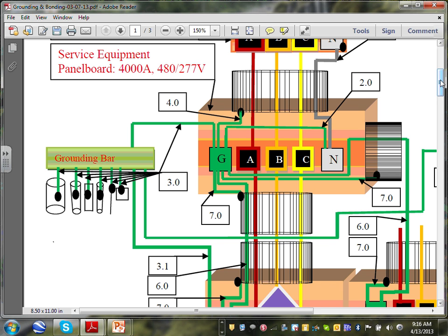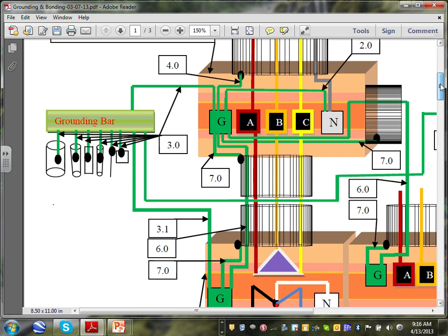Okay, now we've finished at the service. We brought our rigid and we bonded the conduits. We bonded the neutral. We sized the neutral. We sized the main bonding jumper, supply side bonding jumper, and the grounded conductor and the grounding electrode conductor. That's number 1 through 4. That's a couple of chapters in the book, that little thing. They talk about a lot of other details, guys, too.